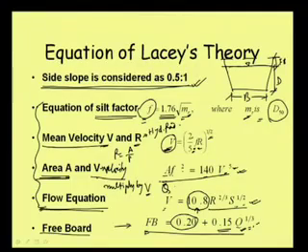For design of channel, in all these formulas we are not talking about q except in the freeboard, but we need to design the channel for a given discharge, and as such we should be concerned about what the q value is.